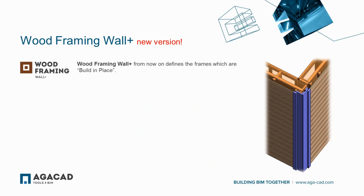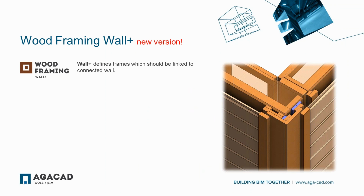Then you can control frames which should be built in place, right? So if we say that those frames should be created in the building place and should not be prefabricated, then we cannot include them into the assembly. It will be scheduled, we will know what kind of frames we need in our project, but it will not be included into the assembly, which should be prefabricated.